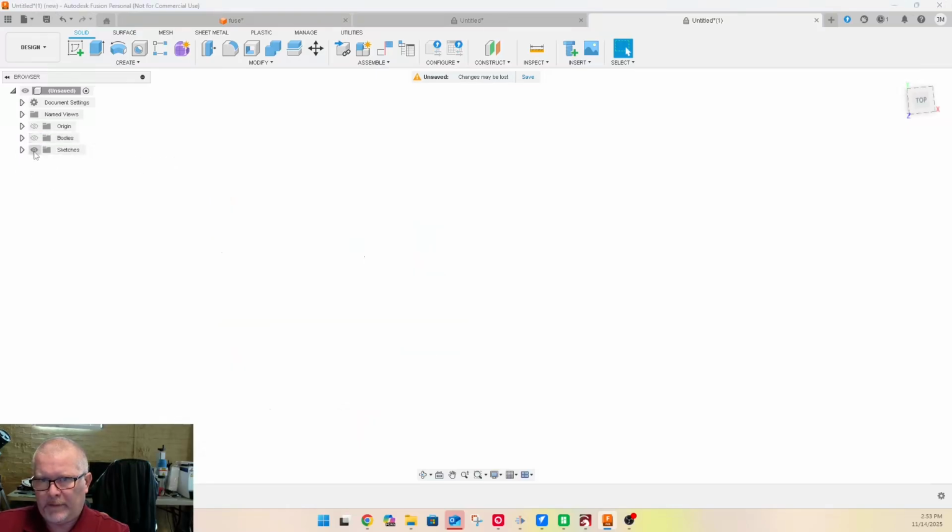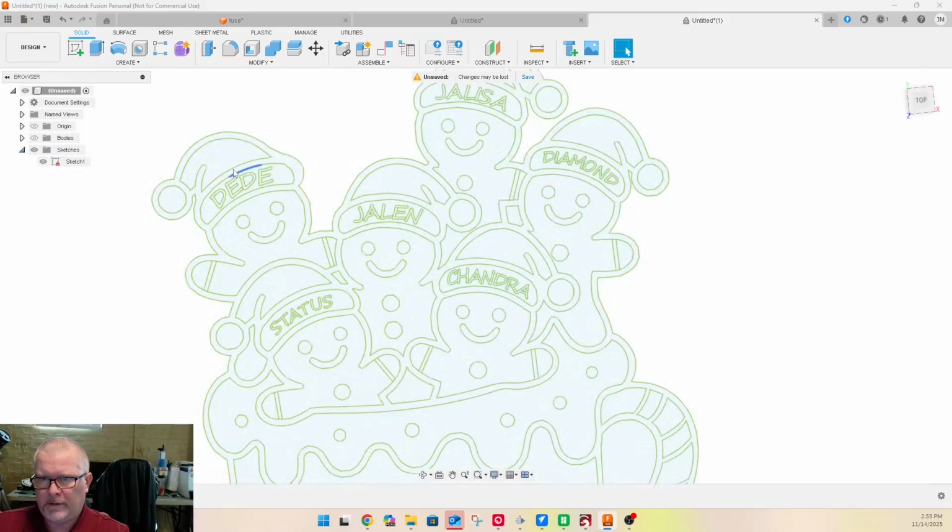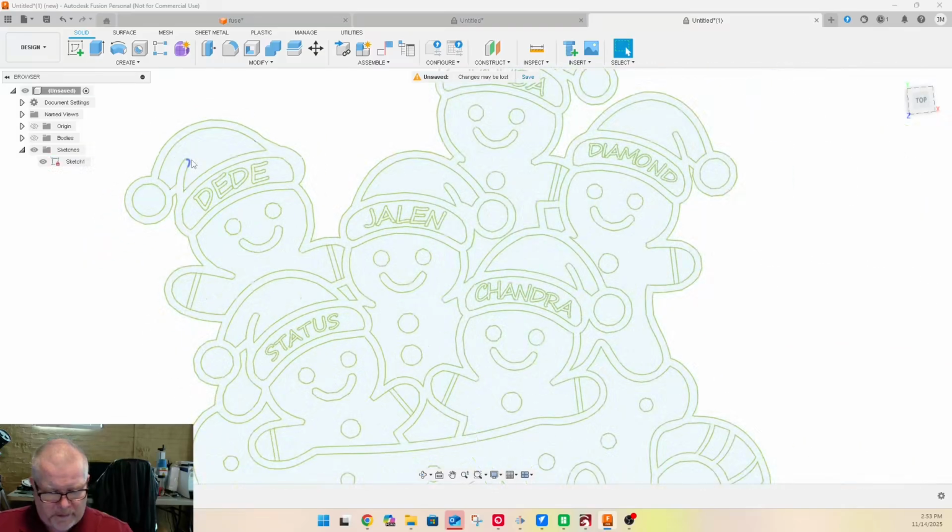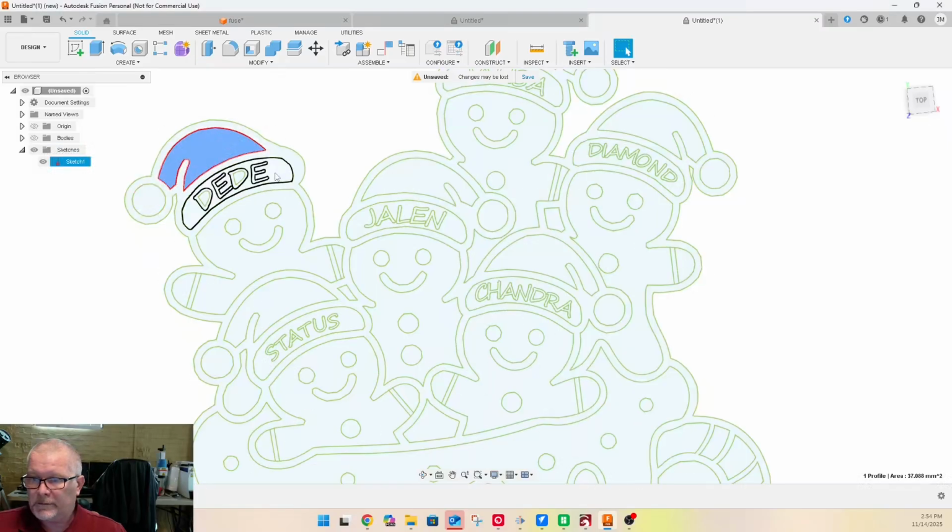So I want to hide the body. I want to open my sketches. I want to unhide my sketch. Then I want to come here and select all the parts that I want to extrude next. And that's going to be the hats. I said Windows key. It's going to be the hats. I'm holding the control key and selecting all of these parts.